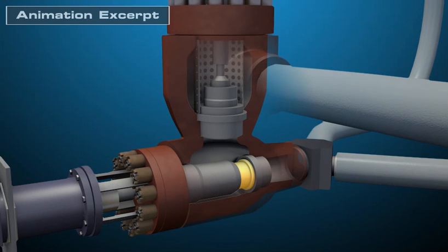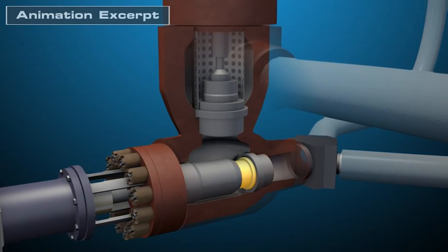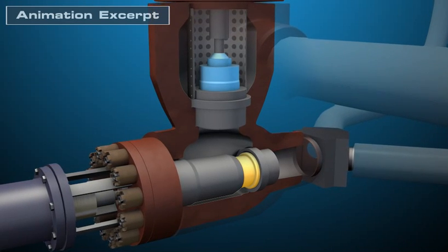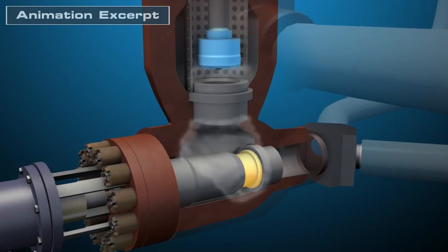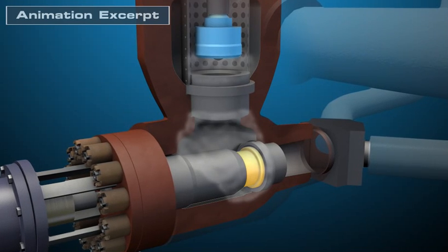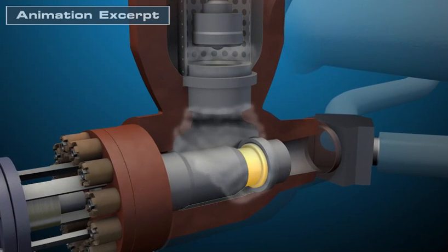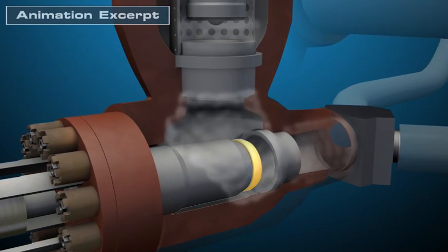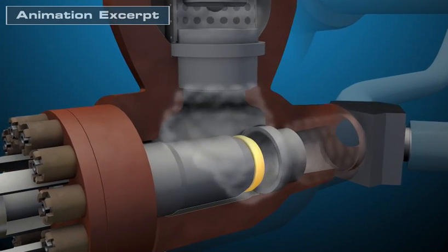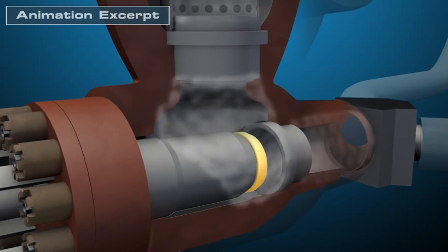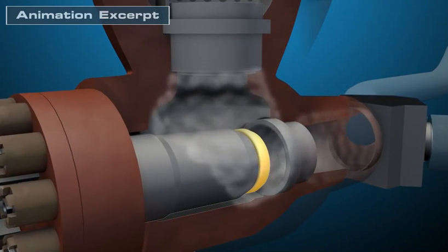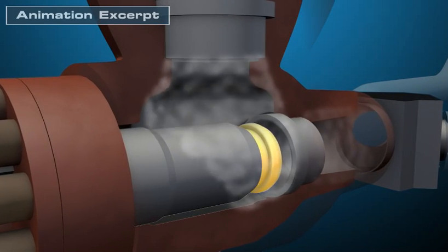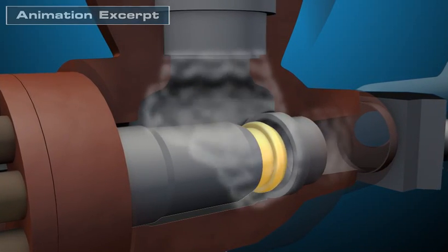The control valve of the MSCV is used to control the amount of steam flowing to the steam turbine. Once the stop valve is open, the control valve will regulate steam flow. As increased generation is demanded, the control valve will open to admit more steam to the steam turbine in order to meet this additional load. Similarly, if load demand is reduced, the control valve will close to admit less steam to the steam turbine.